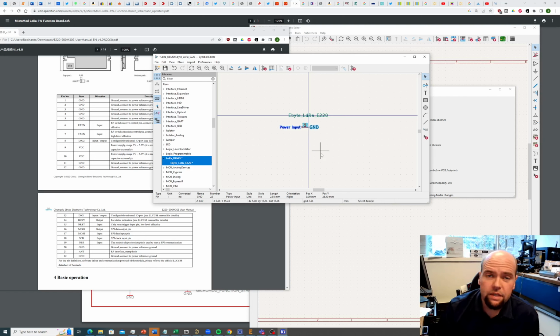So I created all my ground pins. The ground pins are associated with the physical pin on the chip. This is going to tell the software that, hey, this pin does need to be connected to ground. But I also overlapped them, so when we make the electrical connection, it should connect automatically. We'll see in the future. This could be a mistake. I did this a while back, and I feel like there was something that screwed up with this. But we'll go with what we got for right now. It's not the symbol that I'm too worried about here anyway.